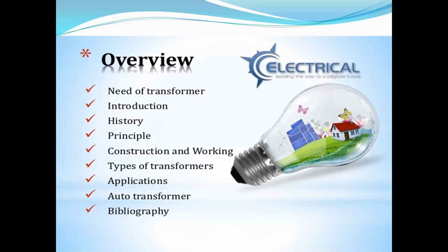Now, the need of the transformer. What is the need of the transformer? Generally, power is generated in remote areas, far from the load centers. If you want to transmit power over long distances at lower values of voltage, currents are high to maintain constant power. If currents are high, losses are also high, because if the current value is more, copper losses are more.